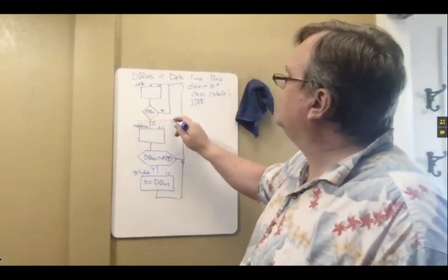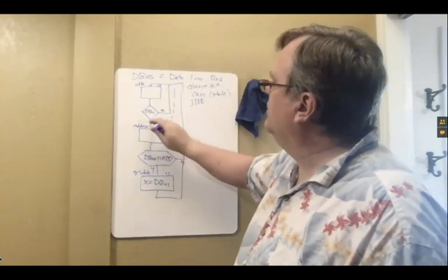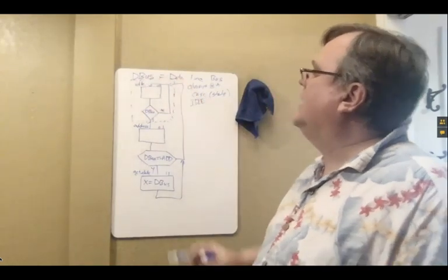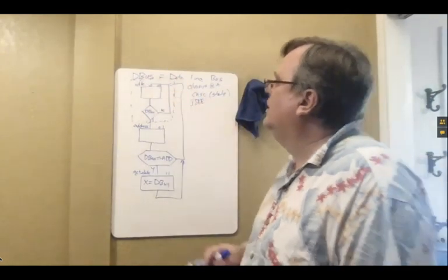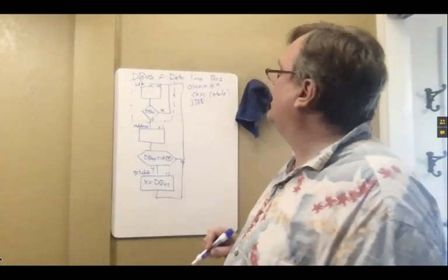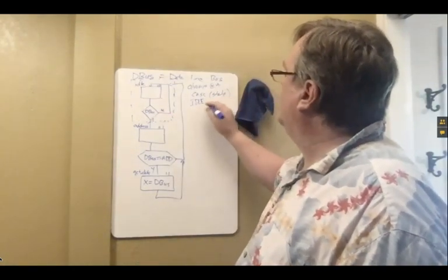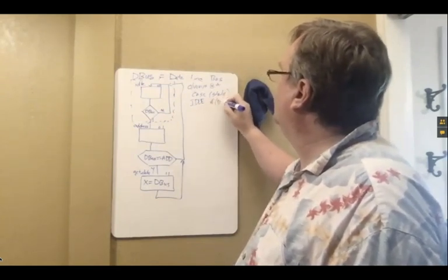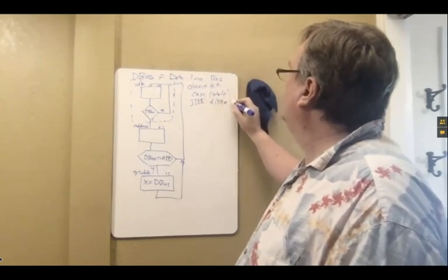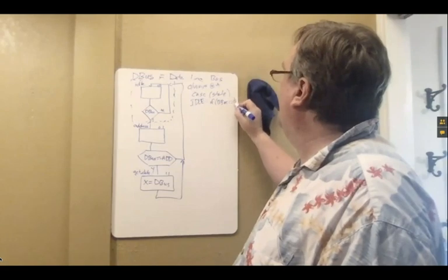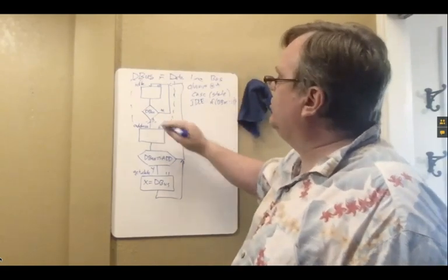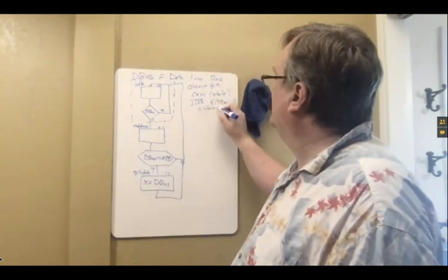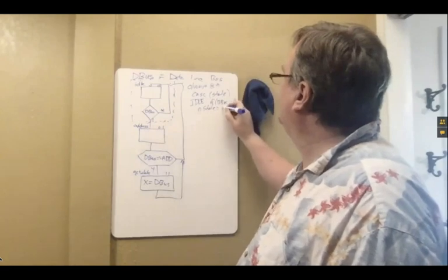And idle is this part here, well, including that one. I can see I don't set it here. The only thing that's happening in idle is this check. So I can then say, okay, inside idle, all I'm doing is if dbus is equal to 1, then my next state is equal to address.